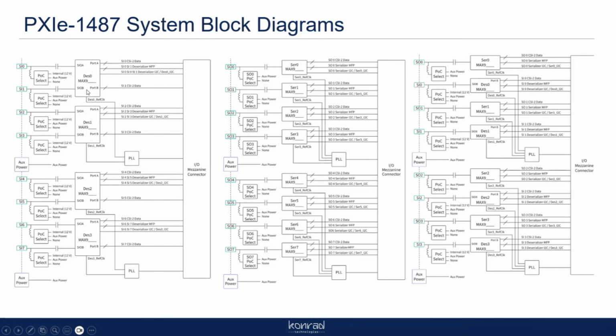You kind of have to have the same settings. So you don't want to have two different cameras set up here. This kind of bit us on one of our projects. I wanted to bring this up, that you can have two different cameras between these two, but if I need different lane rates and stuff, some of that is chipset dependent. And because this is a dual channel, it has to have the same lane settings and same data rates. I can set different sensor settings, but I can't set different lane rates and different feed rates on these. Does that make sense?